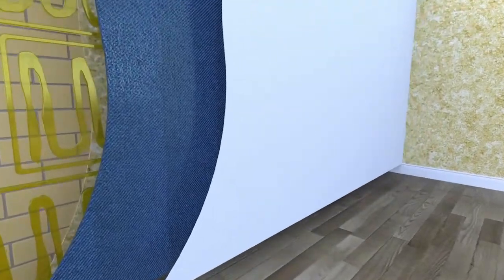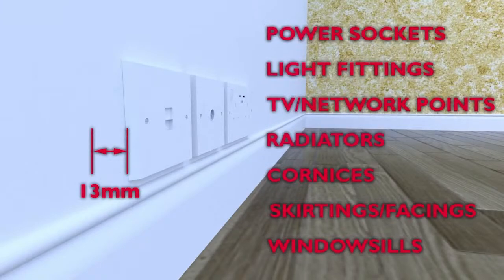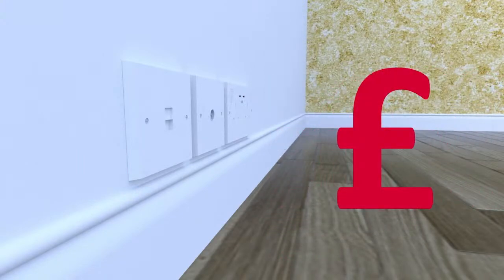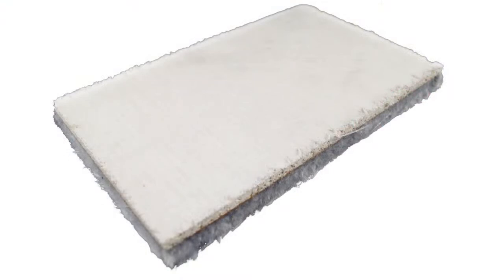Once installed, the system provides a significant reduction in heat loss, with a minimal 13mm increase in wall thickness, meaning in most cases, sockets, switches and TV network points can be left in situ and features such as cornices and window sills can be left as is, with no modification required. It's often the case that meaningful thermal upgrades to older properties are ignored due to the cost and problems associated with such enabling works, and result in unforeseen added costs. Thin systems such as Spacetherm Wall Liner therefore offer specifiers and homeowners a simple option where traditional thermal upgrades are not possible.